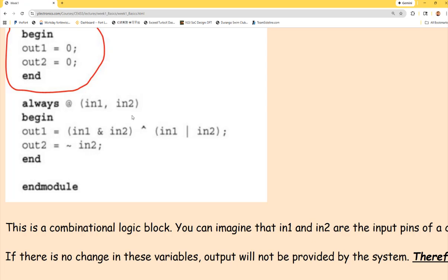You just do whatever the microcontroller has been doing, right? So the hardware is the same hardware as FPGA, but you have a block of memory that can be synthesized by your Verilog, and then you can just load your software to these instruction memories. The hardware you are designing has the capability, has a CPU, has everything, has a pointer, and is able to take out every single instruction from the instruction memories that you design as a piece of hardware, and then send it to the CPU and run the computation for you. Doable, but this is not. This is just hardware, right?